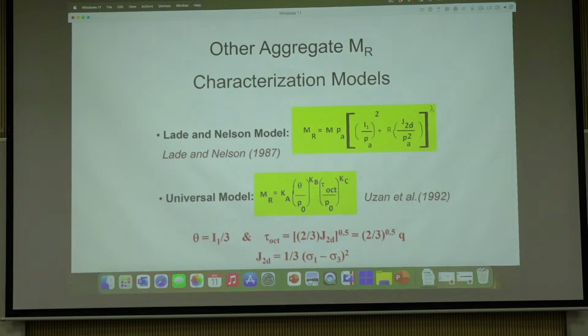No, I mean an invariant is an invariant. It can be a summation, it can be an expression or something, but the point is it does not change with change in the coordinate system or something like that. Whatever you do, it remains the same. The magnitude does not change, right? So that's what the first stress invariant is.